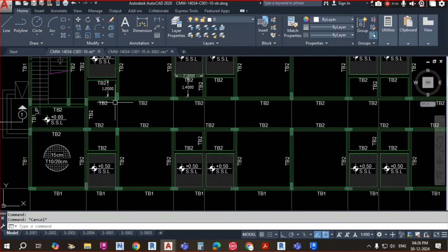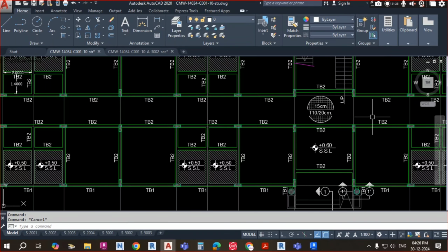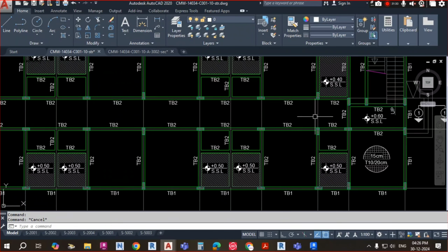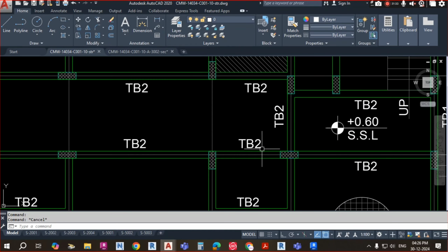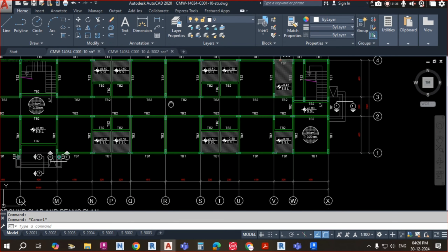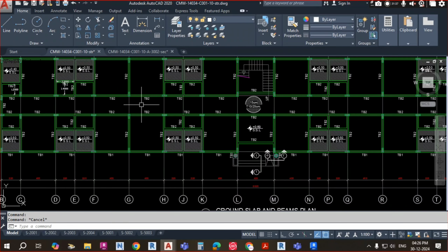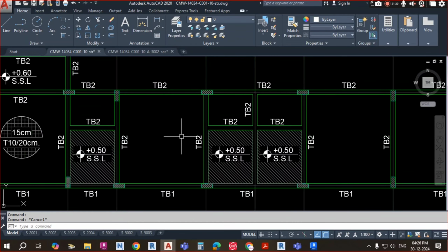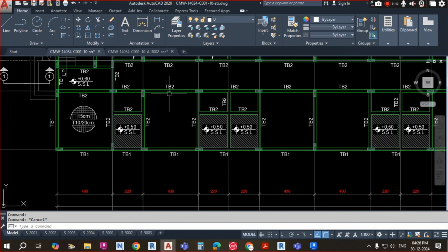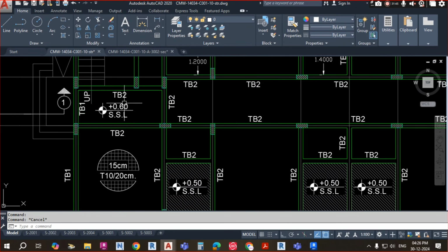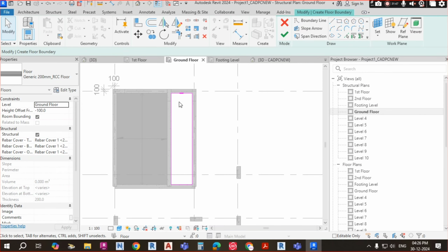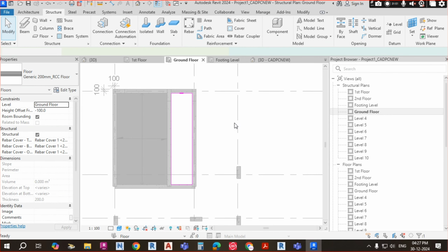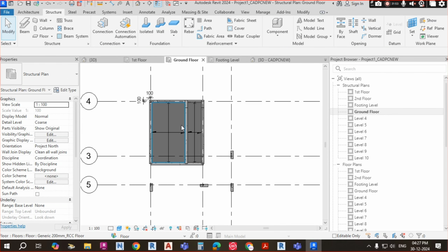Now this is the corridor area. You can see this floor you have to sketch total up to here. So this is only one floor; this total floor is considered only one. But if you come here, this is one floor, this is one floor, like that each and every closing area of the beam you have to make the floor. Okay, so after sketching you just give the minus value and put the tick mark. So here one more floor has come.